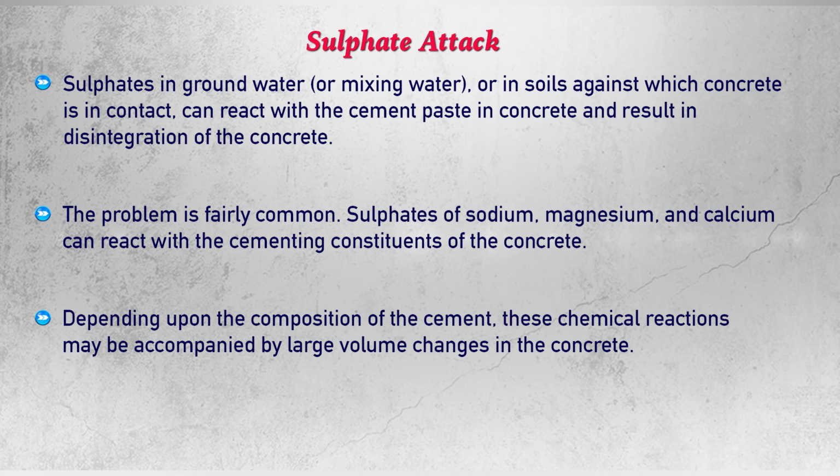Depending upon the composition of the cement, these chemical reactions may be accompanied by large volume changes in the concrete. And you know that volume change in concrete is detrimental because it can cause cracks and the deterioration of the concrete.